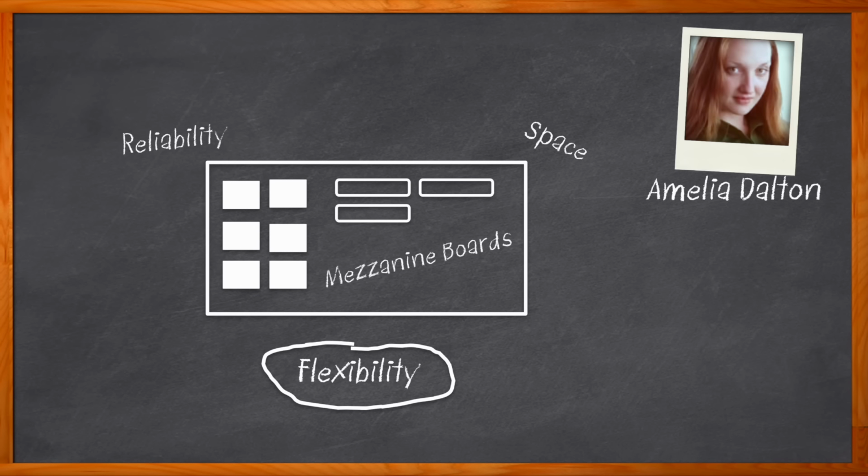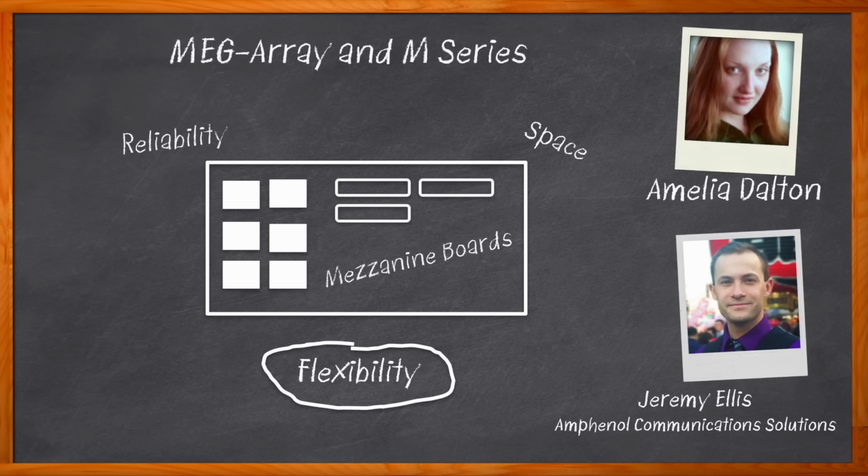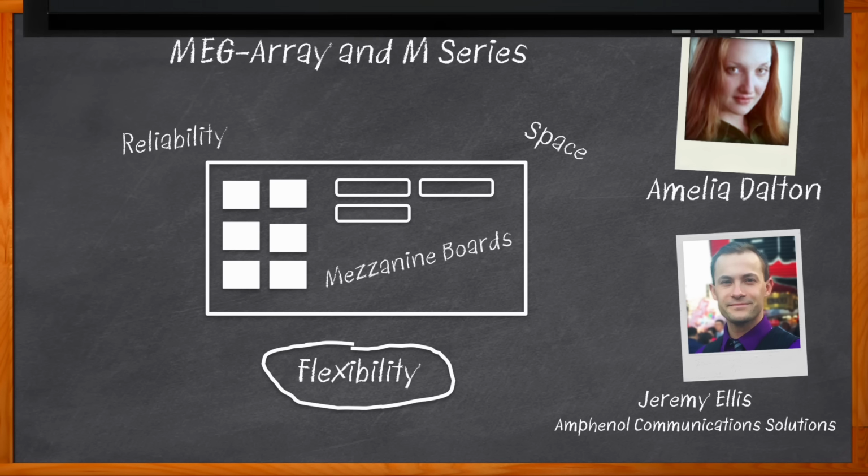In this episode of Chalk Talk, Jeremy Ellis from Amphenol Communications Solutions and I chat about the benefits of Amphenol's MEG-Array and M-Series connector solutions. We also investigate the tooling configurations available for these solutions and how Amphenol's ball and socket BGA interface can simplify board routing, eliminate press fit constraints on VIA, and provide excellent SI performance.